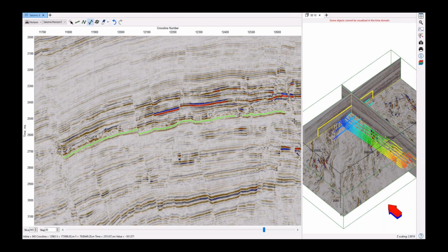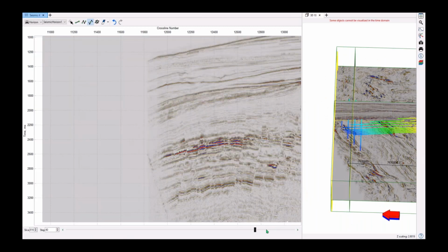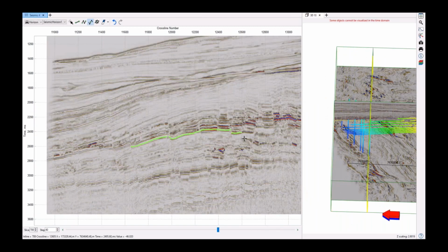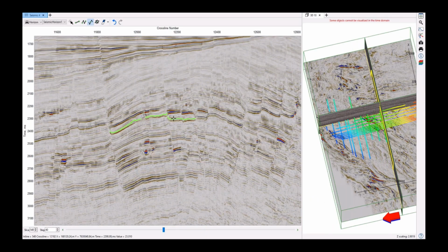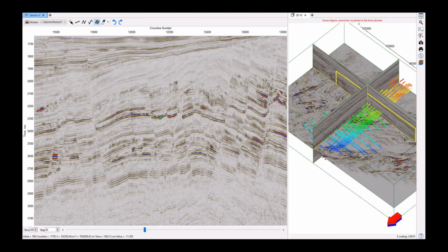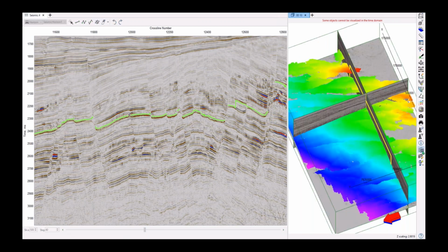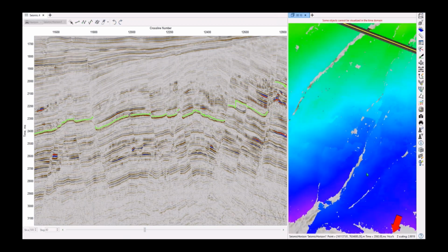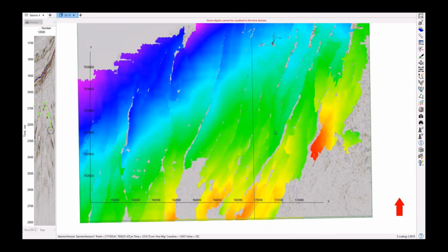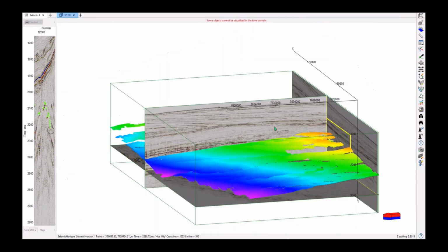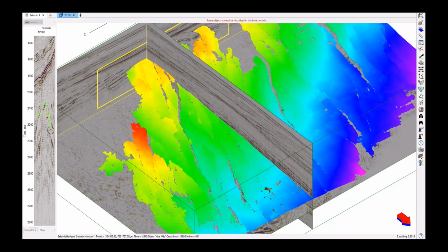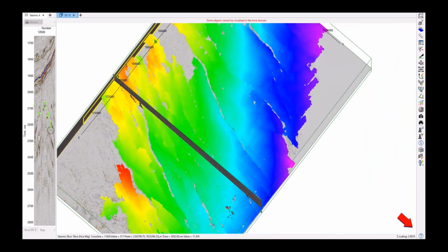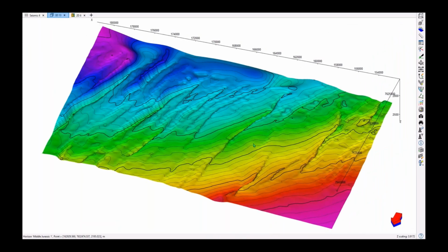For the first part of the webinar, we're working through to build a reservoir model, and normally this will start with seismic. So we're starting off by picking some seismic horizons, and we're also going to pick some seismic faults. We have 2D and 3D seeded auto tracking. We also have nice undo buttons, but we're just using 3D auto tracking to create this surface. We build up our lattice first, create our surface from these seismic points, and then we can push this all the way through to the actual surface creation. This is just what we're doing here.